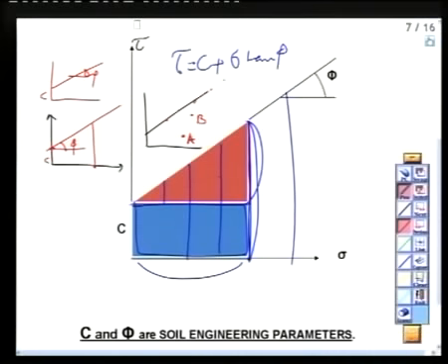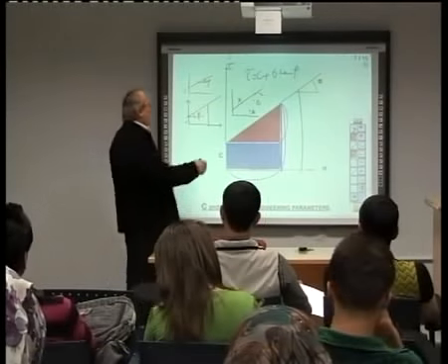As we go down away from the line, I am safer, right? So what about point C? Still safe, but I am at risk, because I'm close to the line. What about point D? D, I'm at failure. The soil can bear 5 kilogram per centimeter square, and I put 5 kilogram per centimeter square. So failure will take place. What about point E?